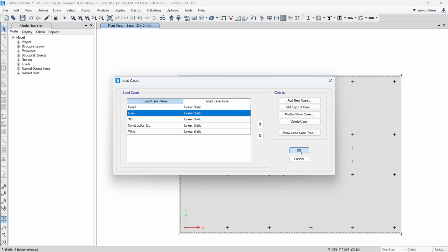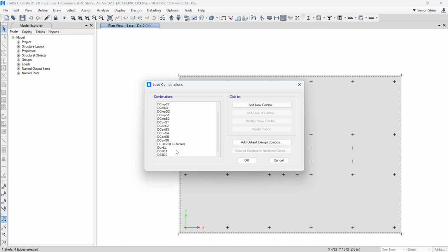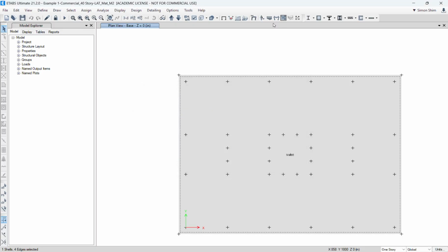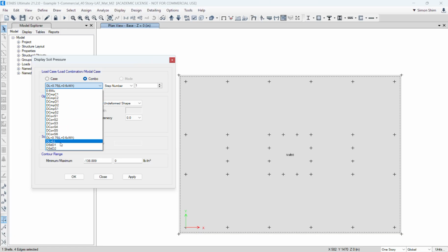All right, obviously there are many structural engineering judgments, so don't just take this for granted. You need to use your engineering judgment. But 0.5 is a good starting point. So what I'm going to show you, first of all, the load combinations: dead plus live load, and also dead plus 0.7 of wind, which is service wind. So those are the cases. I'm going to show you the soil bearing stress. First, dead plus live soil bearing.